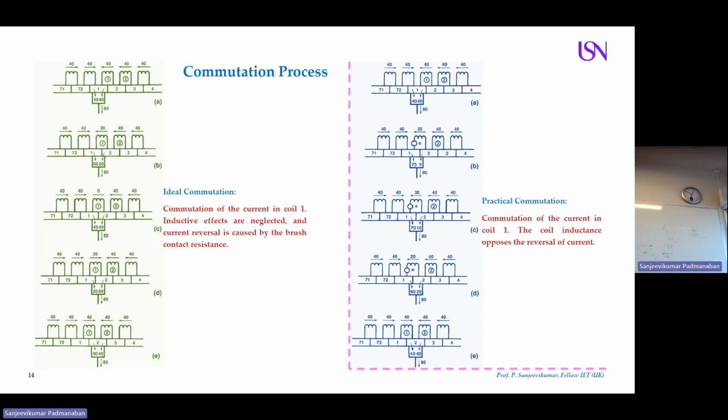You may ask me why this has happened. This is because of armature reaction. I already explained what armature reaction is. The magnetic neutral axis will not be fixed. In a small power machine, there is no issue. In high power, megawatt capacity, very high power machines, the effect of armature reaction is very high. As the machine size increases, armature reaction also increases. Then the value is different compared to small machines. Because of armature reaction, all these amplitudes are varying.